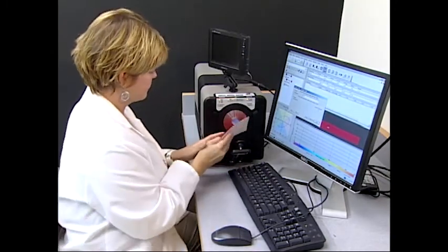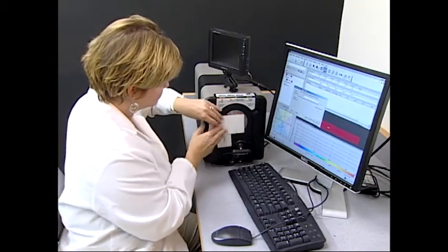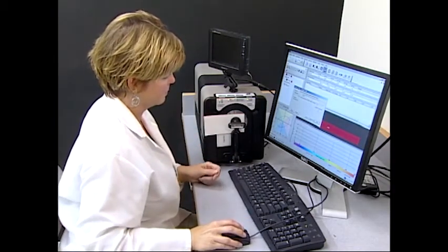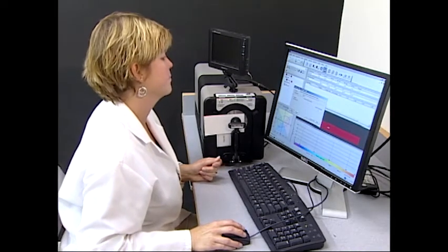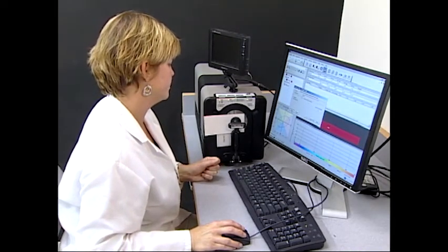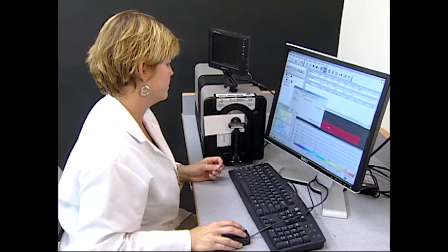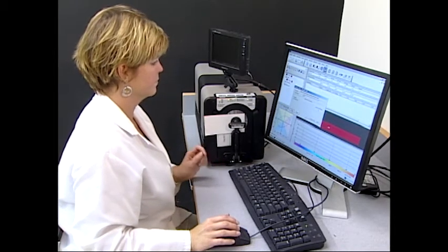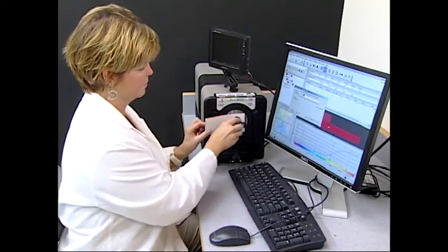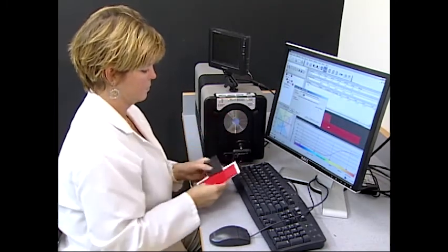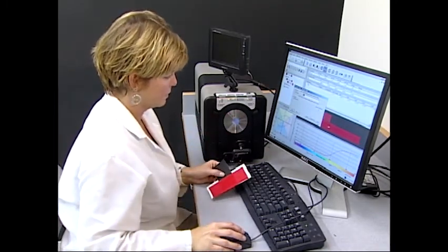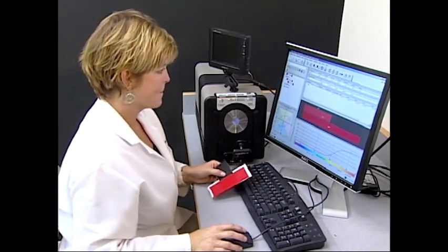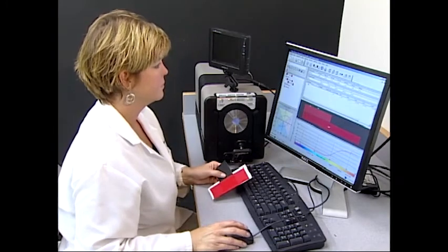Any opaque or nearly opaque material is measured by reflectance methods to obtain a numerical representation of the color of the specimen. Proper equipment setup, standardization of the color measuring instrument, and the proper presentation of the test specimens to the instrument are required to achieve consistent, reliable, and meaningful reflectance measurement results. In addition, calculation of the colorimetric values required for evaluating the results must be performed in the prescribed manner.